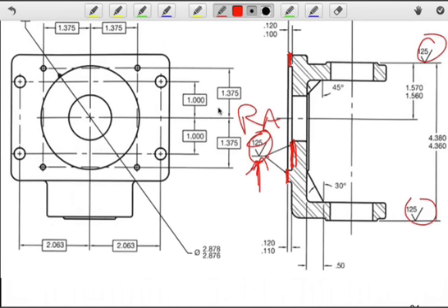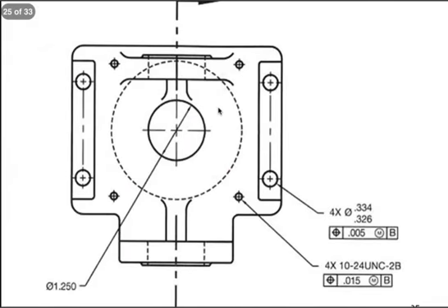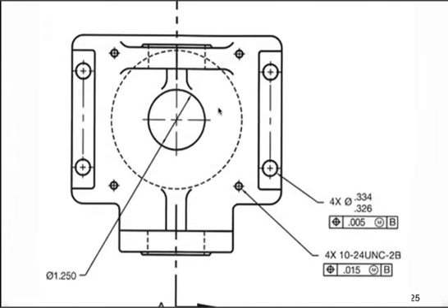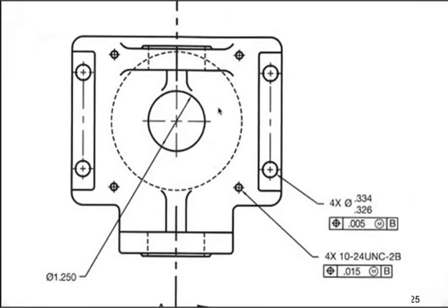And then we look out here, attached to this extension line, which means, again, I've got a 2D annulus about that cylindrical feature, the through hole. And then on this side, the same thing. I have a 2D annulus that has a specification. Both of them are 125 microns for R sub A. So that means when we get to the manufacturing processes, we'll most likely be doing finishing operations on those surfaces. Here, we don't see any specifications in terms of surface texture.